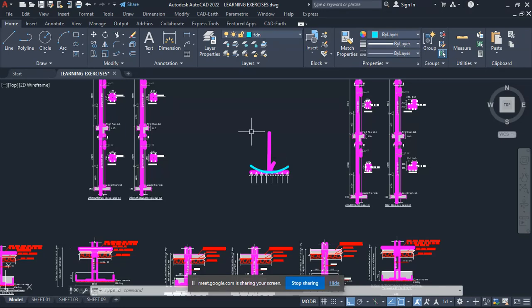From my experience, I've realized most people on site don't give bases cover, and that's a big problem. There's poor workmanship and people just put 1 inch cover. Even on some big projects, I was on one of the big projects in Arua, where they were doing a box culvert, but their spacers were not standardized to achieve a cover of 50. Even in the way they were placing them on the ground, you'd find they are putting a spacer on an inner bar, leaving the bottommost.